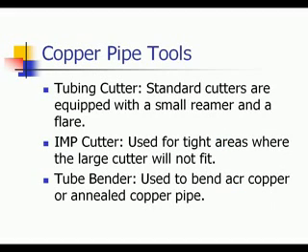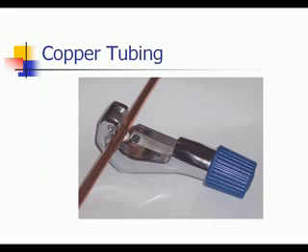Typical outer diameter sizes of pipe are 1/4 inch, 5/16, 3/8, 1/2 inch, 5/8, 3/4, 7/8, and 1 1/8. The difference again between the two is usually 1/8 inch. So 1/2 inch inner diameter, take it to outer diameter, add 1/8. Find a common denominator. So it's 4/8 plus 1/8 is 5/8. 1/2 inch ACR tubing. Okay, again, outer diameter. So again, be careful with the pipe sizing.